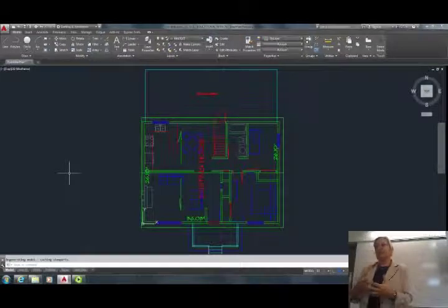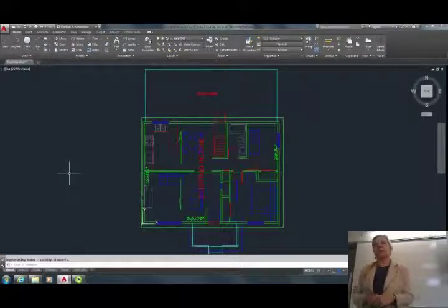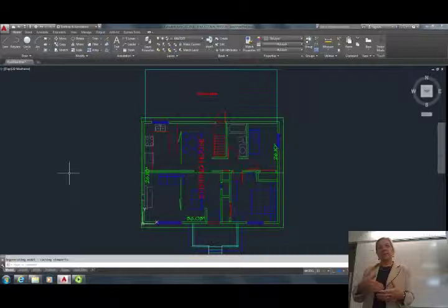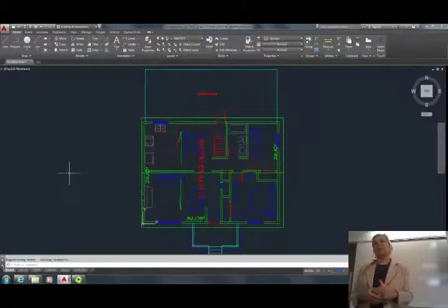But what happened, if you can picture this, all the dimensions and text also got shrunk. So the whole drawing looked good. Will you agree? So for that reason, to have a great portfolio for our small project, I will suggest that we use 1/16 for text size for these small sheets that we're working with. So your last assignment that we discussed on Tuesday is the large plot.